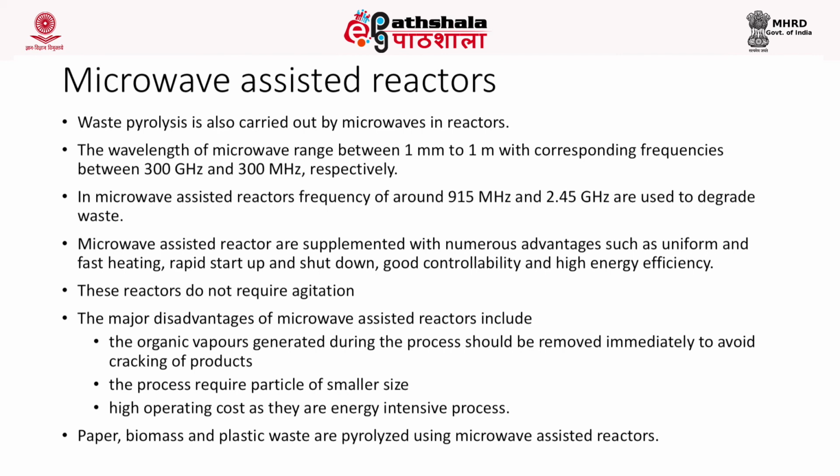Like the organic vapors generated during the process should be removed immediately to avoid cracking of the products. Also, the particle size should be taken care of. Since they involve high operating cost, they are very energy intensive processes. Paper, biomass, plastics are generally pyrolyzed in microwave assisted reactors.